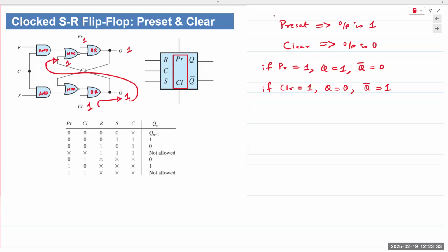Yeah, right. NOR gate is basically 0 plus 0 gives you 0, inverted 1. So both inputs of a NOR gate must be 0 for the output to be 1. For all other combinations, output is 0. So if this single input goes high, output goes to 0. If output goes to 0, and then preset would be 0, then Q would be 0 at the same time.